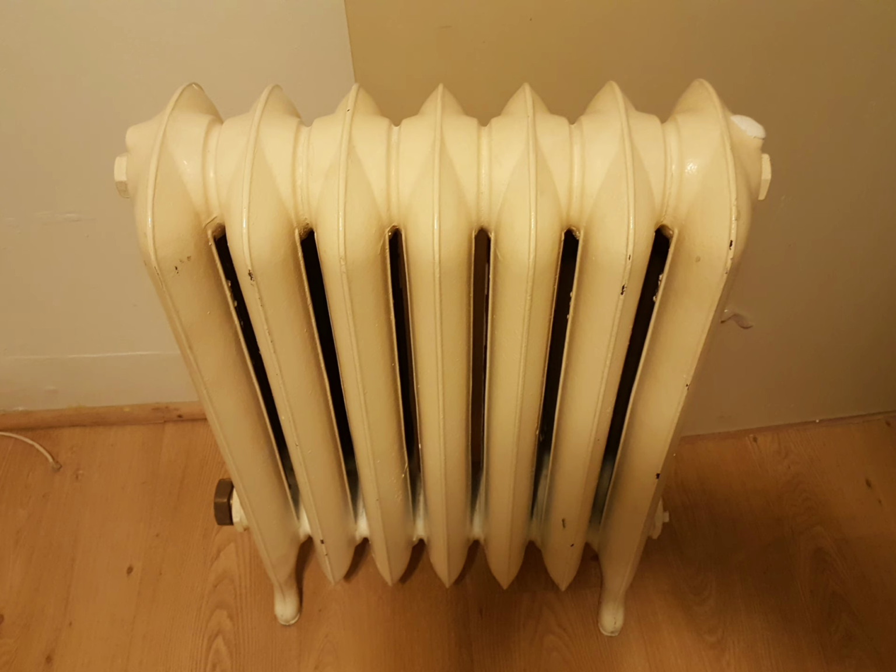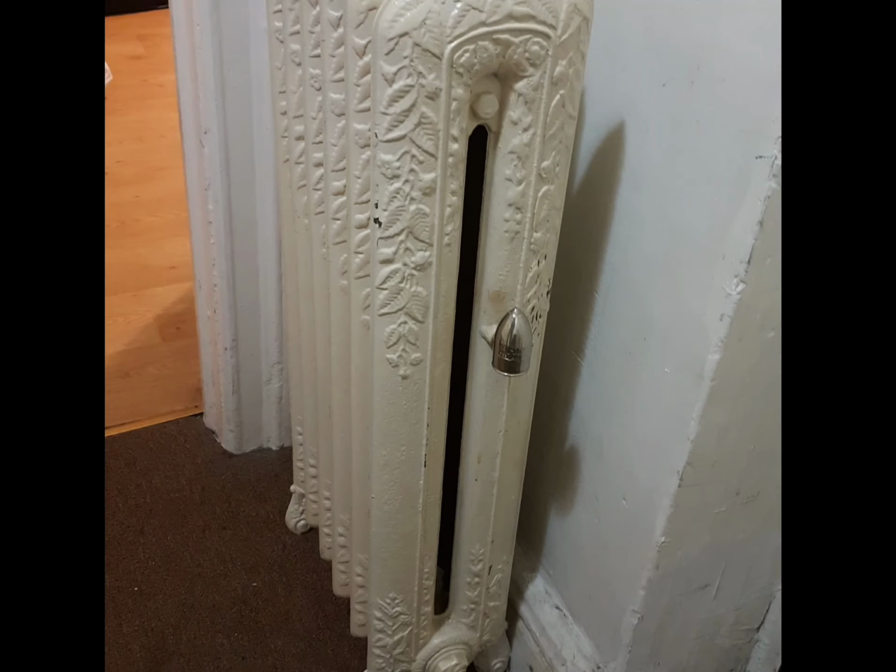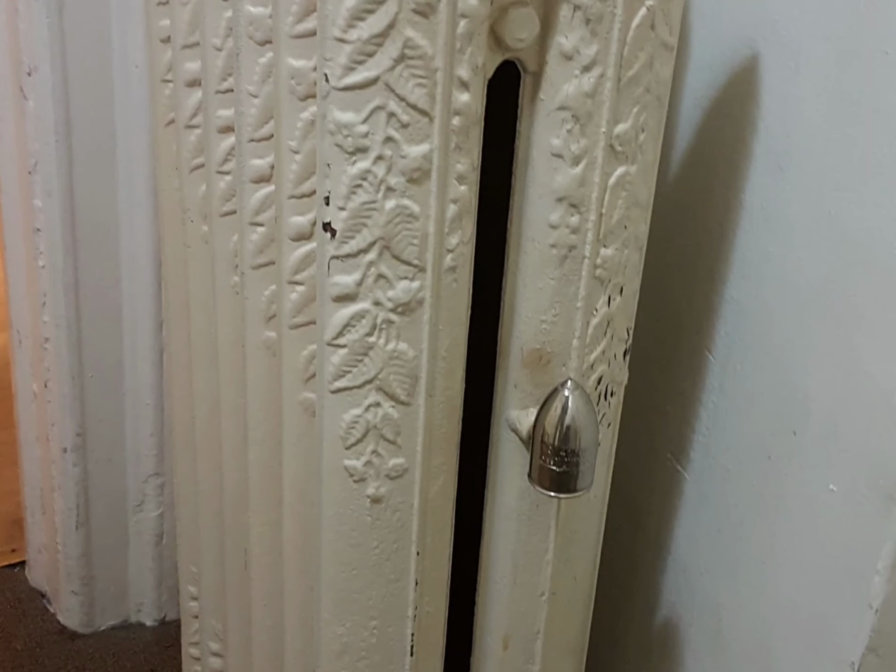When I was a superintendent, my cutout was at 5 psi. If I decided to put my burner on manual and not use my modulator motor, the L91, to reduce the flame and hold it at 2 psi, it would run at 5 psi, and I'd set the cutout to about 4, maybe 3.5 psi. And these air vents, this is another reason I want people to take note of the pressure cutouts that he mentioned, which was between 2 and 5. At 5 psi, these vents would still open up.